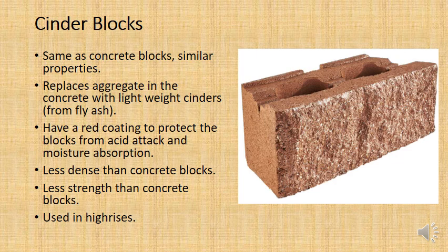And so with a cinder block, after they have made it, they need to spray it with this red coating. It's sort of a sulfur coating, and this basically acts like a paint that protects it from the acid that is sometimes present in rain. And so that gives it more durability. Now, it's less dense than concrete, so that makes it lighter.